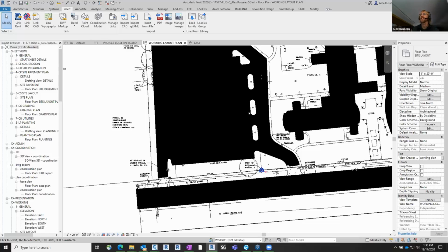I brought it in origin to origin. It had no data into it. So that's where we need to move it initially. After you set up the shared coordinates, that's when you never want to move the file. It should be reliant upon the shared coordinates then.